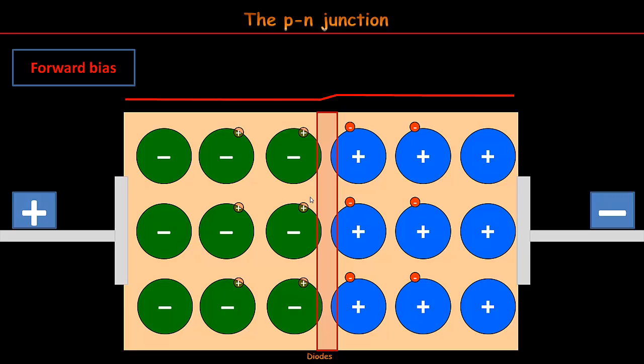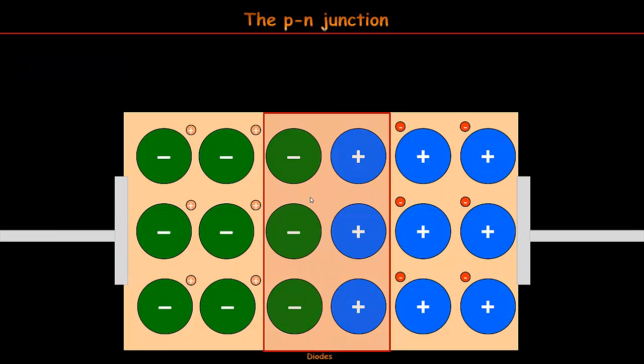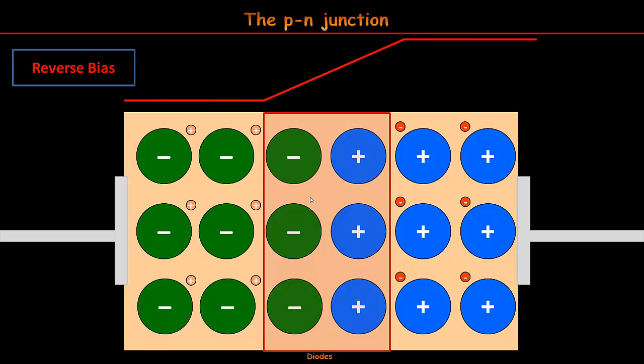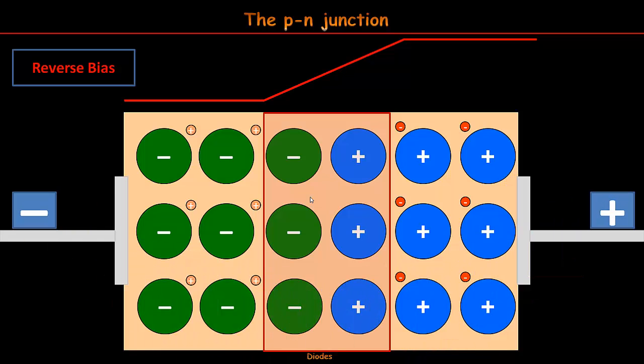To get this situation, the external voltage should be at least of the same value as the barrier. As current takes the contrary direction to that negative charge, going from anode to cathode, we have made a forward bias of the junction. The barrier is also called the forward voltage for this reason. Let's imagine the contrary situation to make an inverse bias. The voltage to be applied is reversed to the previous one, negative at the P zone and positive at the N zone, favoring the voltage barrier in fact.